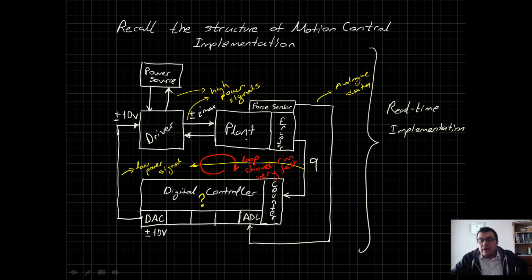Let's say if you're running at 100 Hertz, this means that in 1 second you're running this loop 100 times. Between every two consecutive iterations, you're going to have 10 milliseconds. And in 10 milliseconds, many things might change in a motor. So if you increase this to 1 kilohertz, which means 1000 times per second, then your dt reduces to 1 millisecond, which means that between every two consecutive iterations, you just put a time delay of 1 millisecond. And in 1 millisecond, it's really hard to create big disturbances in your plant. So that was our motion control structure.